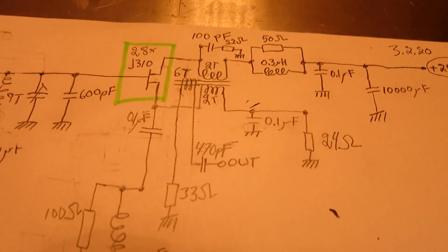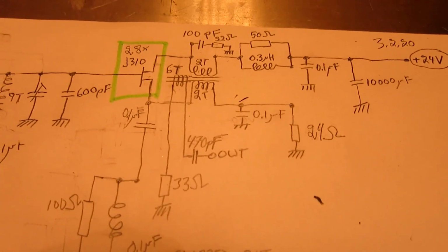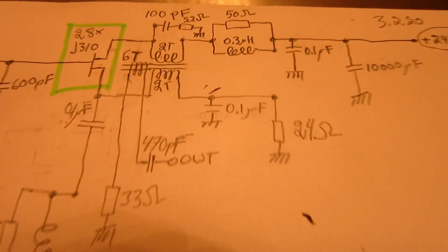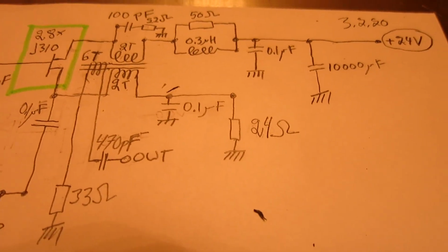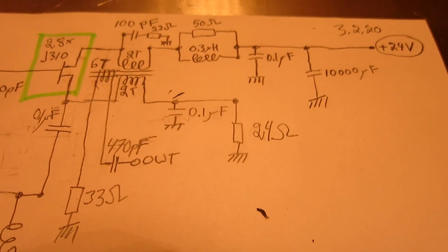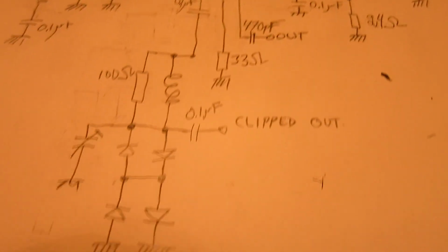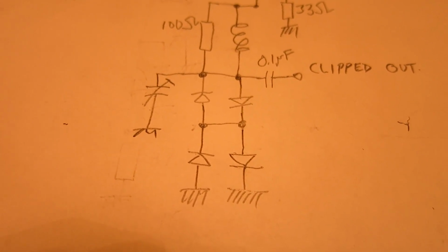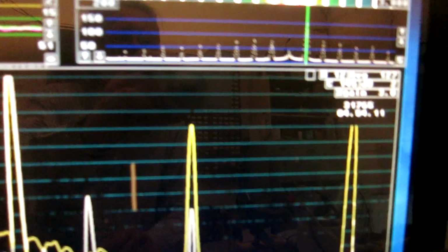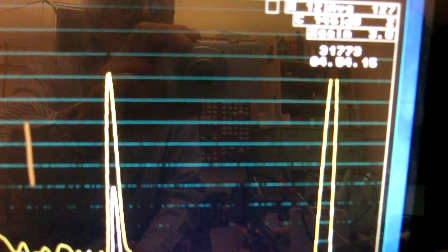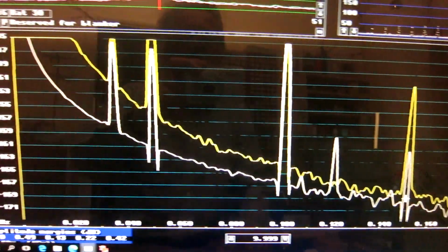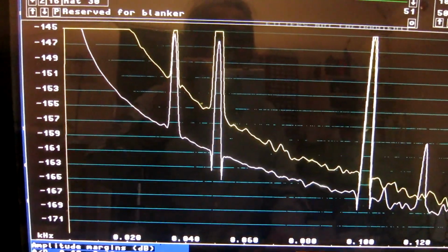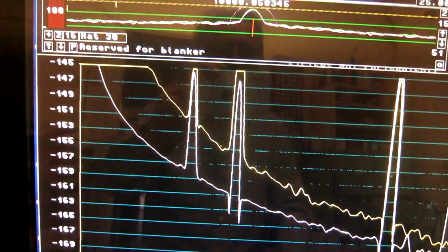As it turns out, it is favorable to have the output amplifier running saturated. So I have modified accordingly. The source resistor is now 24 ohms, and I have increased the drive level a little by connecting like this. This is nearly 5 hours, and the screen looks like this. Yellow track, the upper one, is phase noise, and the lower is amplitude noise.